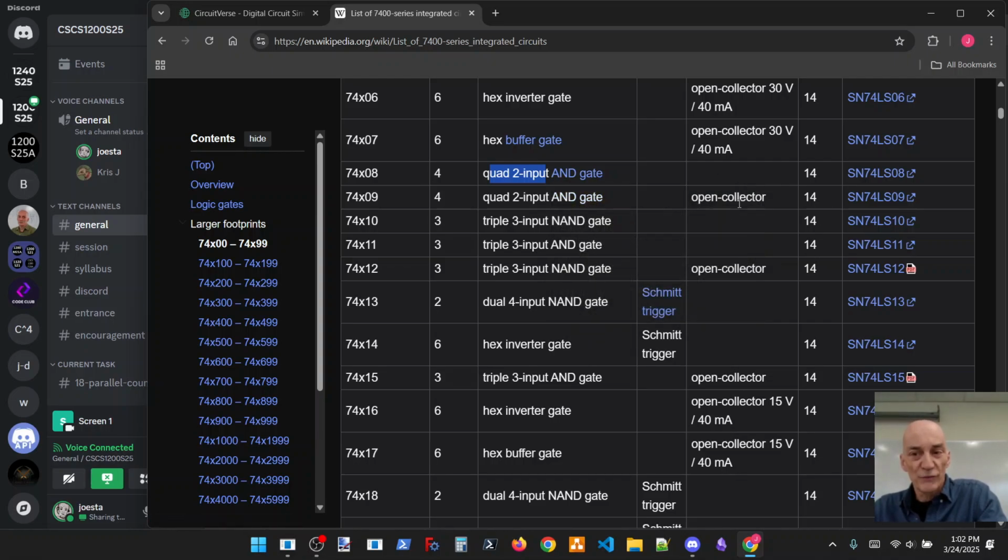The outputs were different. That's an electrical thing that I feel like I should probably just skip over, but I can't. Remember in CircuitVerse, we said the rule is you never connect 2 outputs directly together. Right? Because what would happen if one's trying to be a 1, one's trying to be a 0?